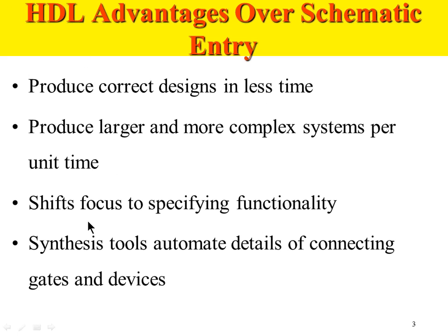It will shift the focus to specifying the functionality of the design. When we did schematic design, a lot of time and energy was spent worrying about the gate connections. What is the input of a particular gate connected to? What is the output of that gate connected to? Is it correct? Is there some connection missing? A lot of energy and time was spent on the connection aspect of it. Whereas with HDLs like Verilog or VHDL, we spend the time specifying the functionality of the design, and we let the synthesis tool worry about the connections.